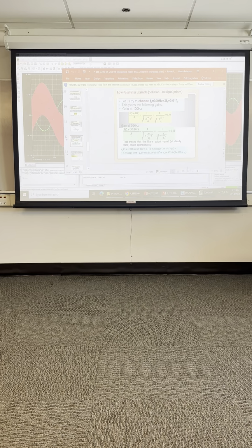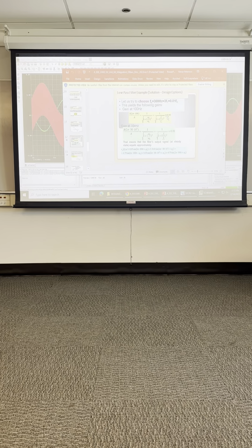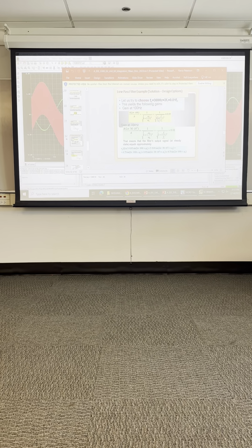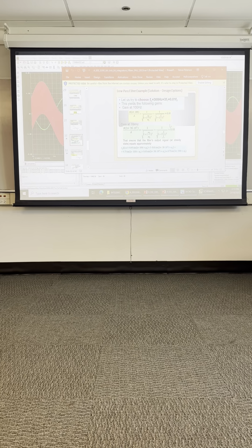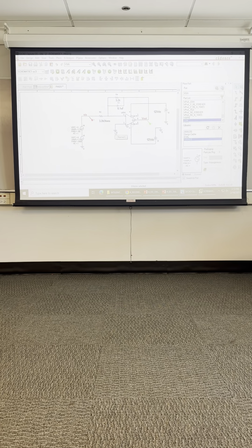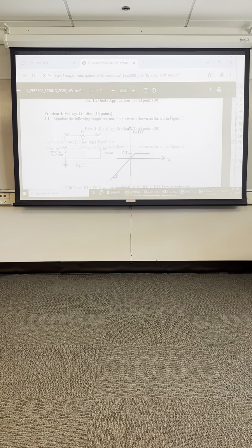Once you get this, you have to come up with a creative way of explaining, when you mathematically calculate it, why this filter should reduce the 30 kilohertz, and do your numbers resemble what you're predicting in your paper analysis. It's really just a matter of doing a transient analysis and an AC analysis. The other parts are very straightforward diode simulations.